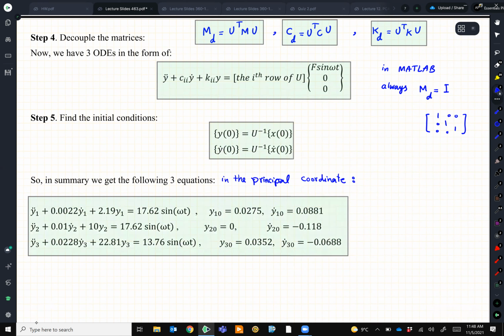All right. So what happened? We have a 3 degree of freedom system. We derive the equations. We use MATLAB to find the modal matrix. That modal matrix did the magic for us and decoupled these equations. I showed you in the lecture before that you can also use the modal matrix to transfer your initial conditions. Remember, now we have to move everything to the principal coordinates, the ones that are in the direction of the eigenvectors, right? We just use math and the rest is easy.